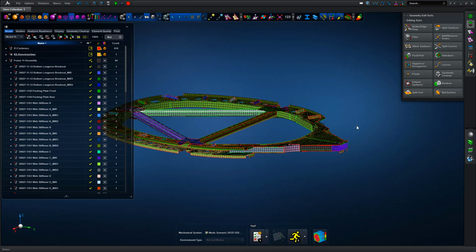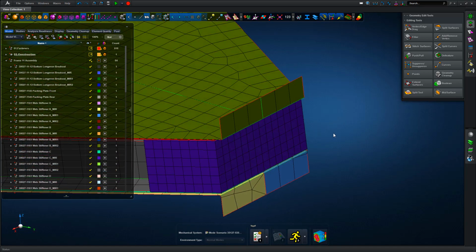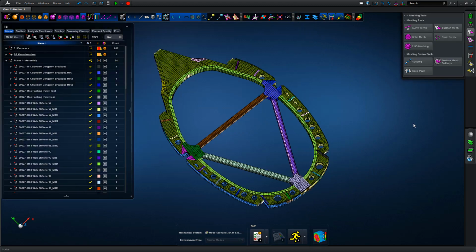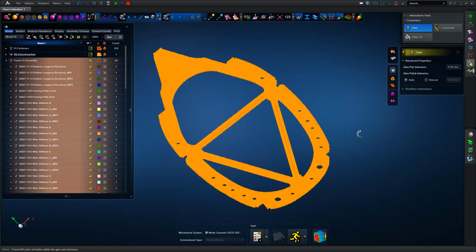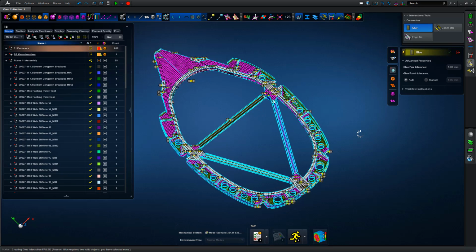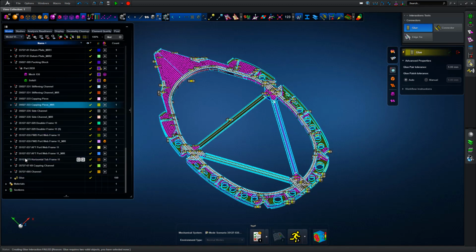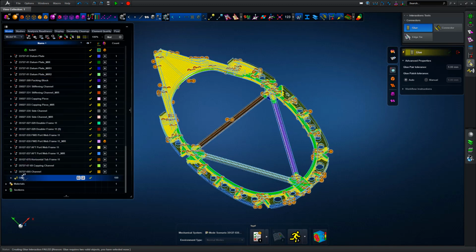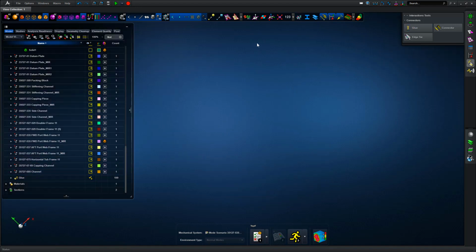Okay, so once we've got the full assembly defined from a mesh perspective, so we've got all the thin shells manipulated, quality checked, and properties assigned, and also thick shell or hex mesh for the thicker regions, we can now glue the full assembly together. So using the default glue pair tolerance of 5mm, that looks for entities within that tolerance and glues them together. You may well have seen one of the previous tutorials or webinars where we looked at explicit connector technology, and part of that was focused on the glue, which is effectively an internal MPC definition defined on an MSC Nastran base level.